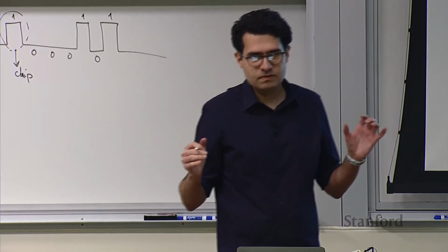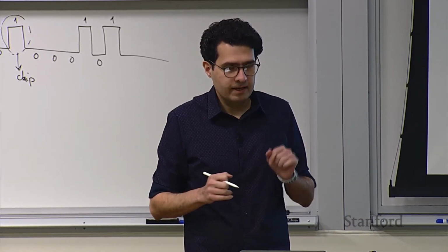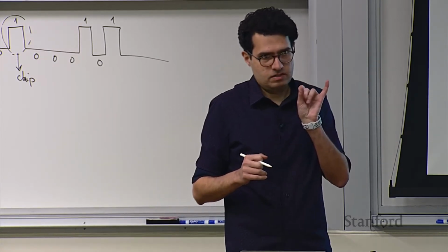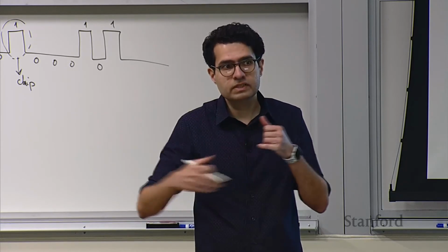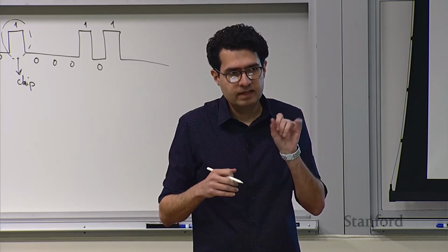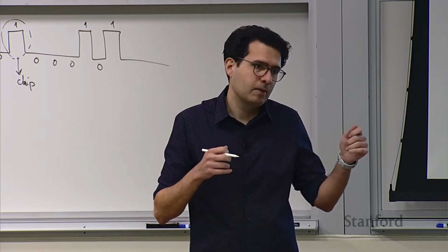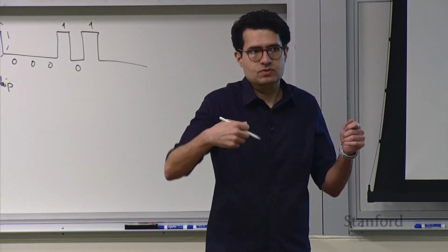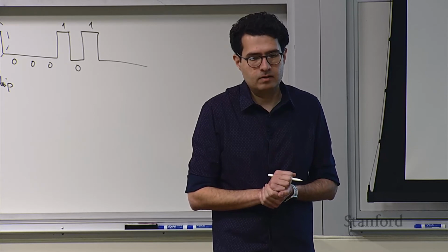So the way the receivers operate for the PY code is that they can operate on short sections of the code. They actually wait and acquire the minimum amount that gives them enough signal-to-noise ratio that they can use for ranging. And that's how it operates.